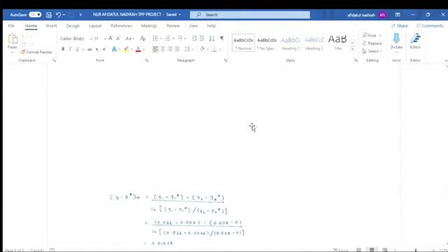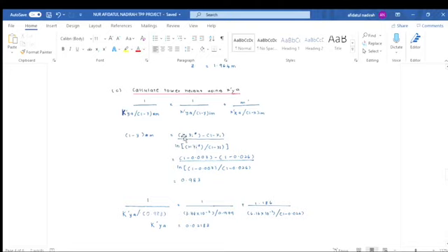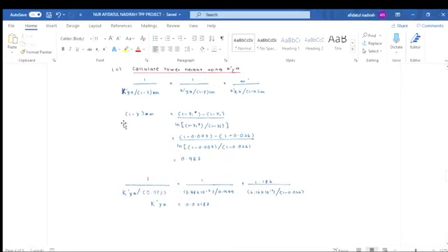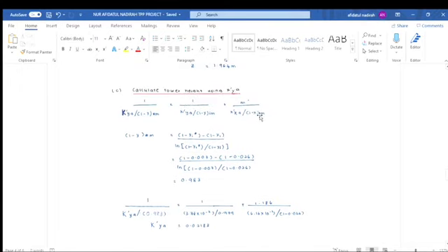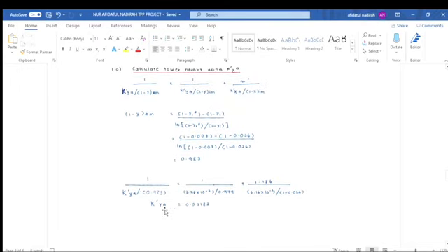So back to the equation. We substitute the values of y1 star and y minus y1, and we get the answer 0.983 for 1 minus y star m. So we substitute in this equation, and the only unknown here is K capital YA. After we calculate it using basic mathematics, we get that K capital YA is equal to 0.02183. This is not the final answer, as the question asks us to calculate the tower height, which is z. K capital YA is only the coefficient.